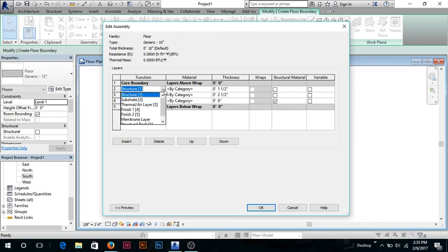Okay, let me see. Thermal, air layer, finish. We'll do a thermal, and then we'll put this under finish. And then this is structure. So altogether, that is 10 inches. That tells you the total thickness. So as I change the numbers here, 4-inch, it automatically changes it here. So you don't have to sit and do any calculations. It does it all for you, which is great.